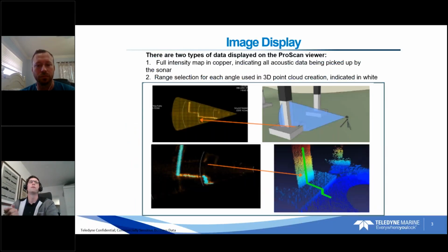The biggest hurdle a lot of new users have with our sonar in general, or any sonar really, is interpreting what you're seeing in your live view. As you recall from last week when we went over the BV5000 hardware, this is a vertical 1 degree swath. So it's a small slice of your environment you're looking at in the live view.